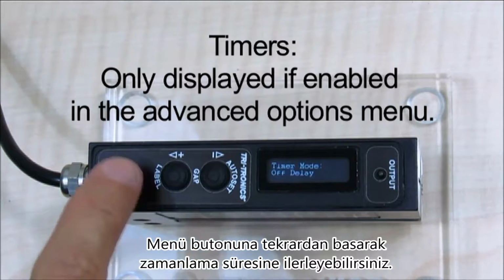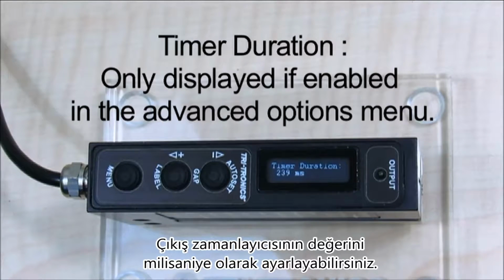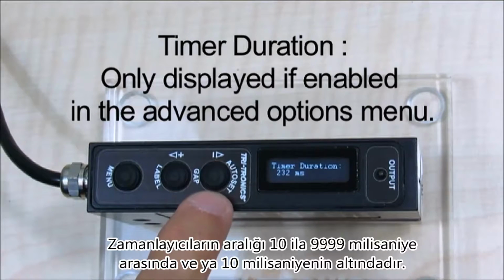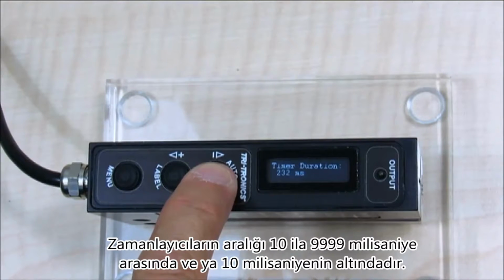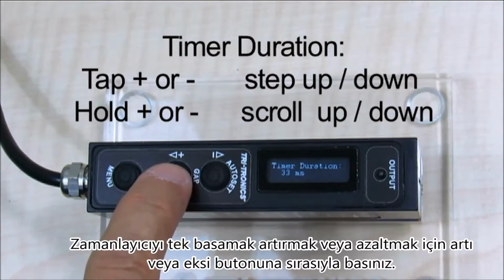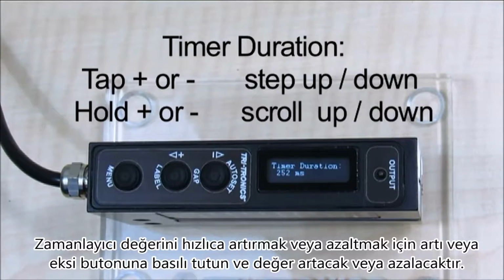Tap the menu button again to advance to the timer duration, where you can set the value of the output timer in milliseconds. The timer's range is from 1 millisecond to 9,999 milliseconds, or just under 10 seconds. To increase or decrease the timer by 1 digit, tap the plus or minus button respectively. To rapidly increase or decrease the timer value, press and hold the plus or minus button, and the value will begin to scroll up or down.